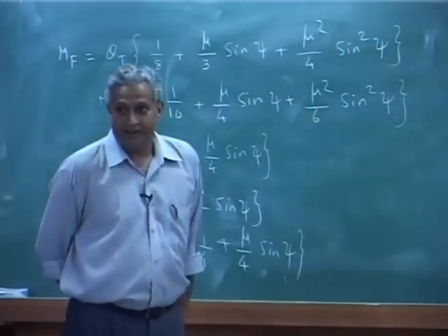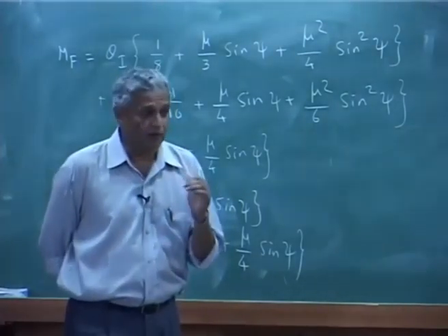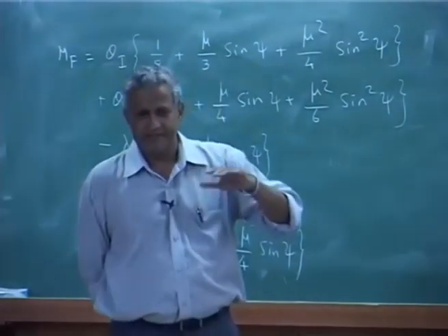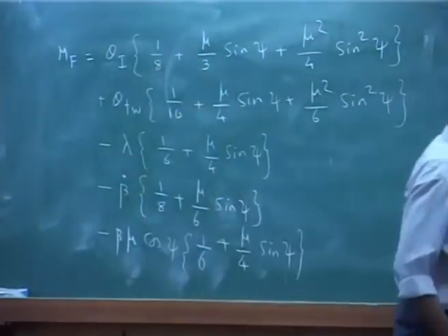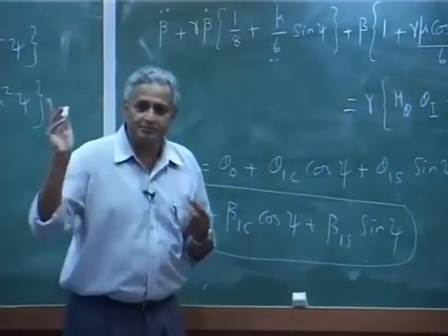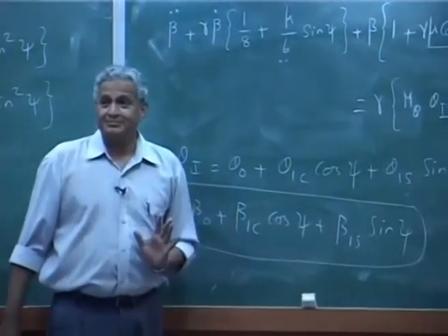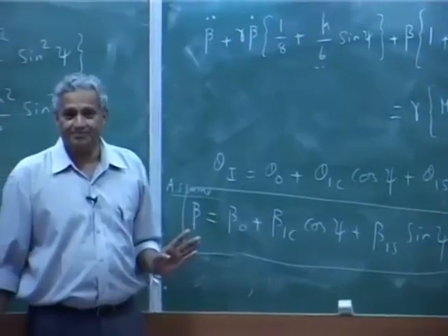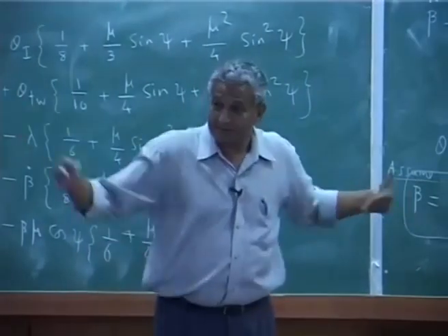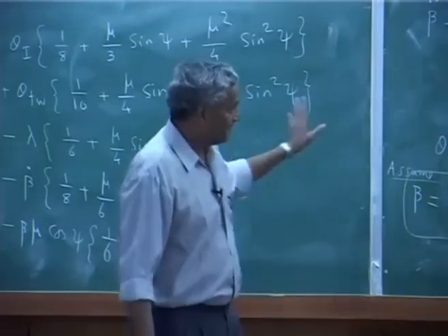Okay. Now this is called harmonic balancing because you are looking for steady state response. Steady state means these are fixed angles. There is no change. As the blade goes round and round, what will be the harmonics of flap motion? It's like a steady state solution. Okay, it is only the particular solution, there is no transient part. Transient part is 0 there.